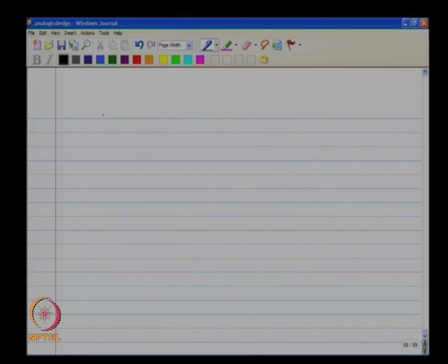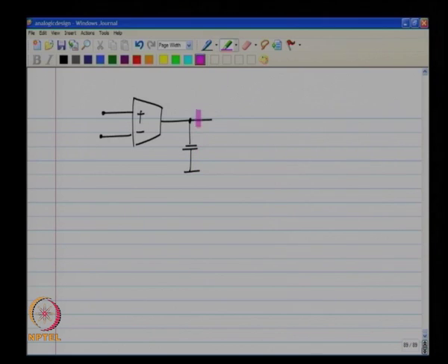So, finally, the picture of the op amp is as follows. We have the transconductor which drives its output current into a capacitor, and to avoid drawing any further current from this, we use a voltage buffer.